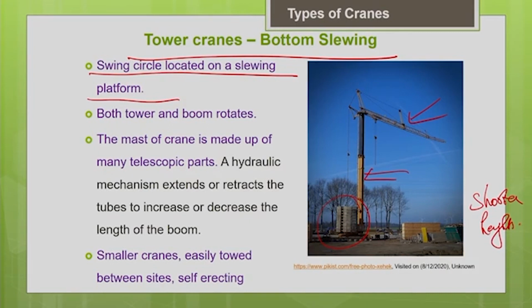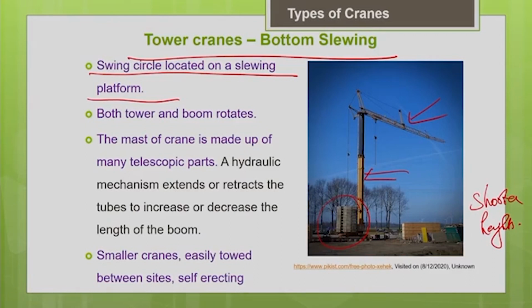But the main advantage is it can be easily mobilized to the site, because there are many hybrid varieties available, like you can easily fold it and take it on the public highways, or foldable type or telescopic type, where you can just extend or retract the length of the boom. All these provisions are now possible, which facilitates easy mobilization, erection and dismantling. If you need the crane for a shorter duration on the project site, this will be the right choice.